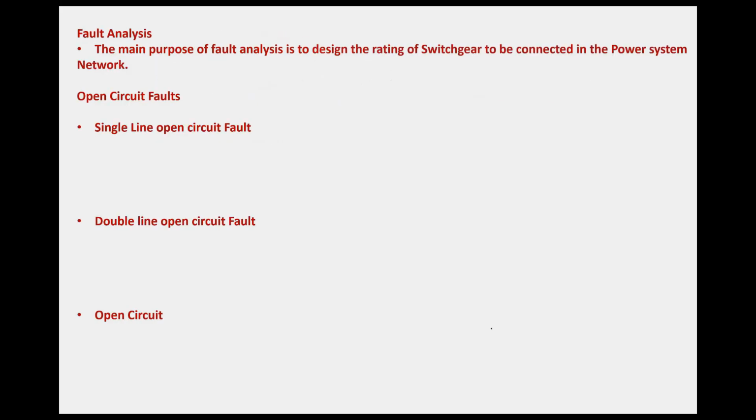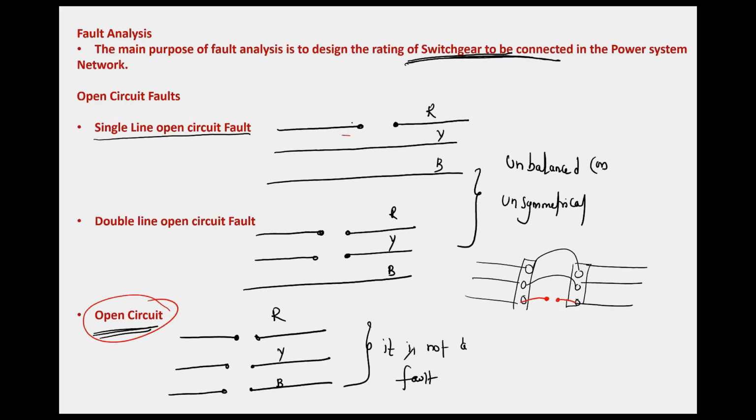That means, in this case, if this conductor is open, then the voltage of the Y phase conductor and B phase conductor will overshoot. They will face an over voltage problem. So there is a chance of insulation failure for the equipment that are connected to these two phases.